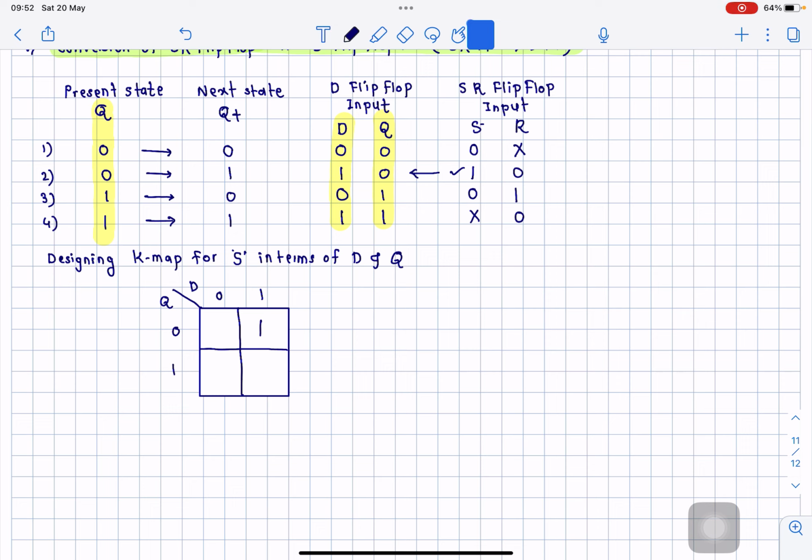And we also want to take the don't care condition of S. The don't care condition X will exist when the D and Q inputs are both 1. D and Q both are 1. So this is X, right? So we can combine these to form a group. So the equation for S, directly, from this 1, 0, 1, 1, D will remain and the Q will get cancelled. S is equal to D, right? S is equal to D.